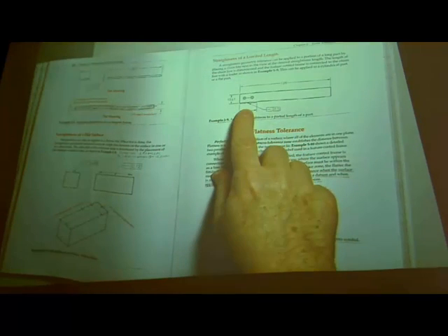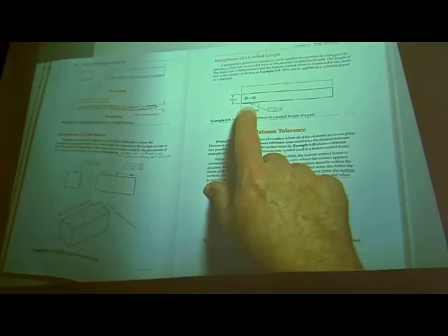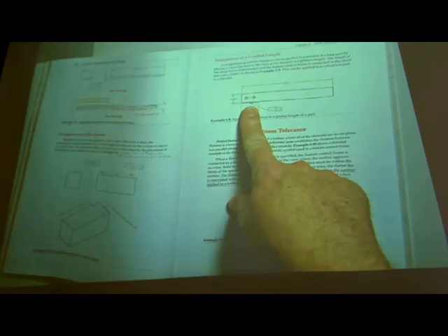Then we may just control it on one end of a part, and we identify it. They're showing a center line, a thick center line. So I think that just turned out wrong for them. I'm not sure. I was thinking a chain line is a thick center line. Suddenly I was thinking it was like a phantom, that a chain line was a phantom that was thick. I may be wrong in my memory. I have to go back and verify it in the old manual to be sure.